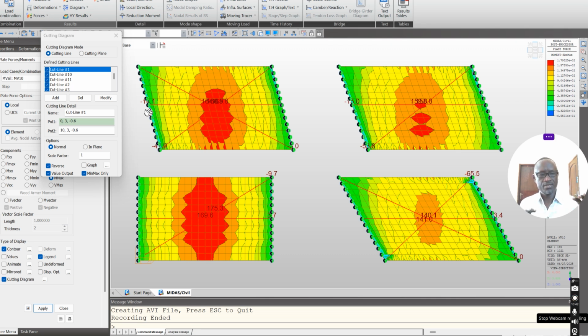That means your reinforcement needs to be bent in a way to take care of the stresses at the end of the deck slab. So it is very important, and that's why we were saying the use of U bars is very important to take care of that. So it is 14, while at the obtuse angle it moves up to 42, from 10 to 42, 4 times.